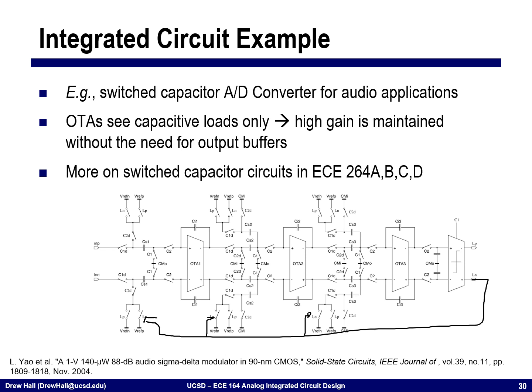What you'll notice is that we have several OTAs. In this case, we have 3 of these operational transconductance amplifiers that I was talking about, and you'll notice that there's no resistors. There are only capacitors and switches. And so this is what's known as a switched capacitor circuit, and I'll talk about this in just a few slides about how switched capacitors work.